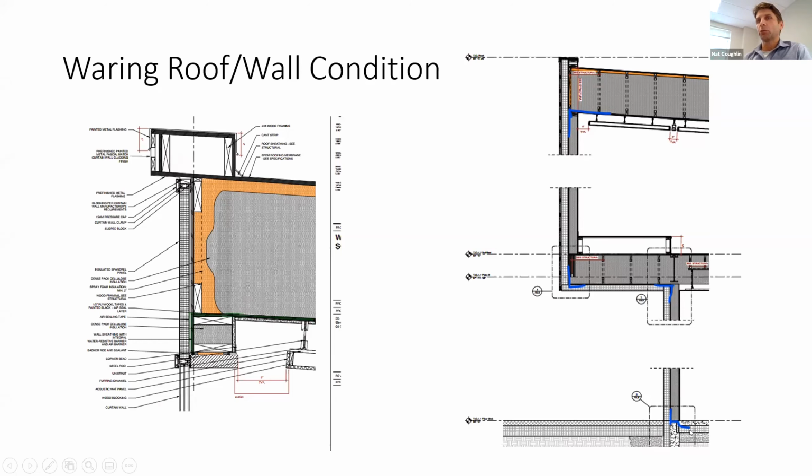And then on the right is where we had done the same thing sort of internally. We took a cut of the building and in the blue had said, okay, this is the line of the air barrier. It's on the underside of the truss, then the outside of the zip. It goes under the overhang. Like we followed it all the way down. And then we actually had a tape detail that brought us all the way in down to our vapor barrier.